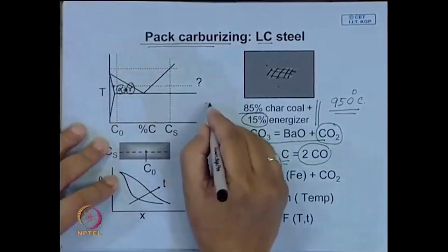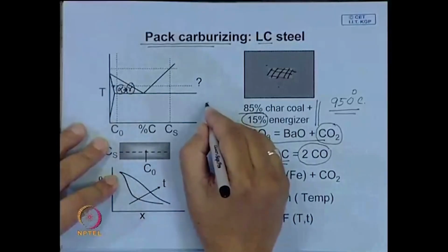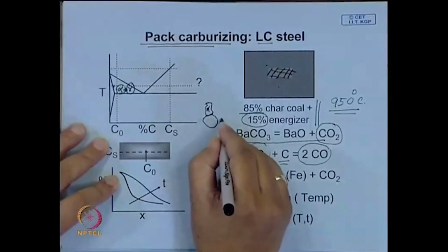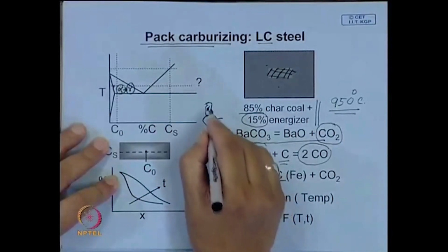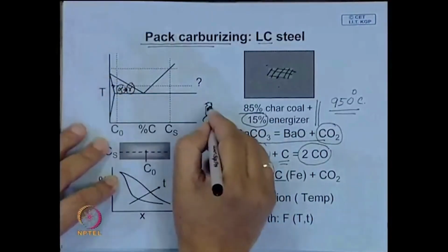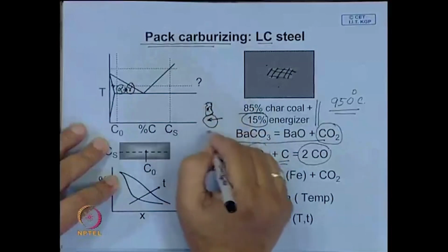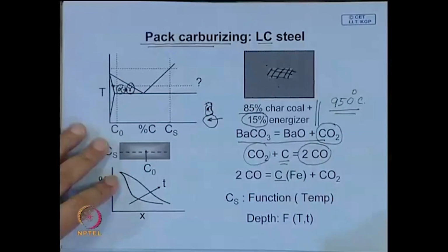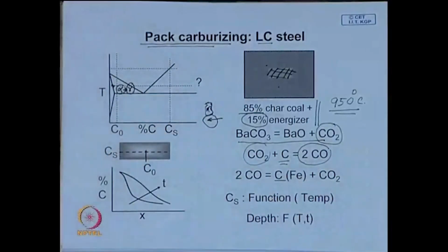So, on the surface you have ferrite grains, and you also have austenite grains. So, you will find the carbon will diffuse more here and very little over here, because ferrite solubility is very little. So, here again the problem will be that carbon distribution is not likely to be uniform in the structure. So, this is a problem.